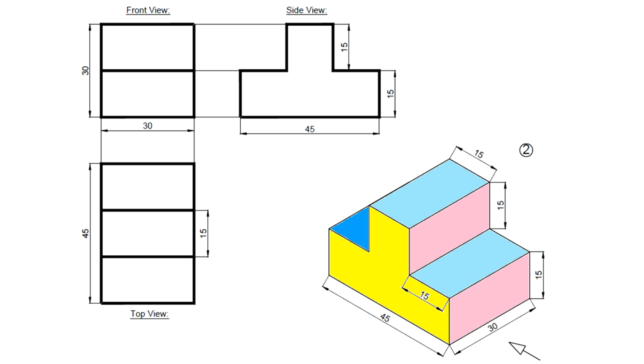So if you draw the front view of this red color, the front view will look like this. So 30 by 30, and these two surfaces are separated, and these two are separated, so that will be separated by this line. Then we need to draw the top view. If you see the top view, the same principal surfaces will be visible in the top view also, but now these two will appear one after the other horizontally. Because the arrow mark is given here, this becomes the front view and this becomes the top view.